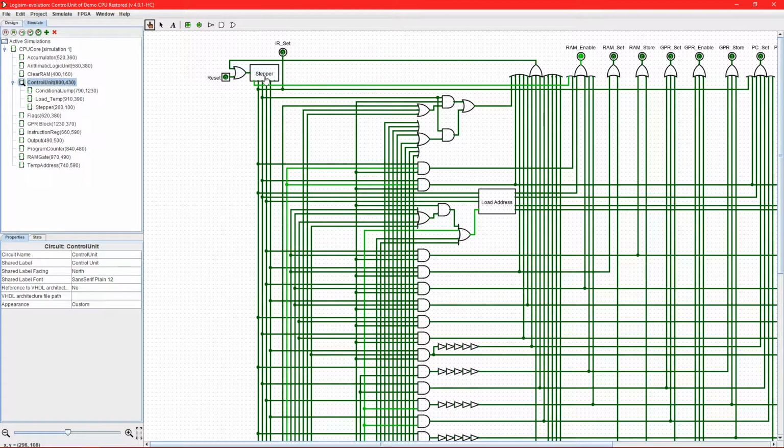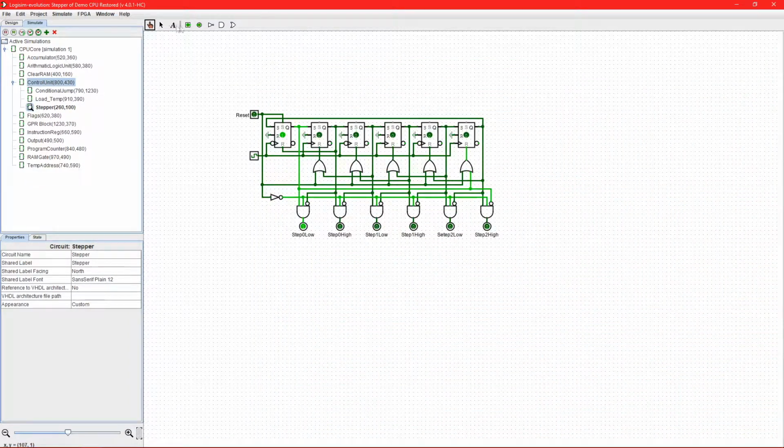So if we go inside the stepper, we can see that it's much simpler than the previous one. So most of the time, the stepper will be reset on this step. So the moment this thing goes high, a signal is sent to reset this, which sends this thing high and this thing low so quickly that you can't actually see it. Otherwise, the reset signal is going to be on this, and this will go high then low so quickly that you won't be able to see it.